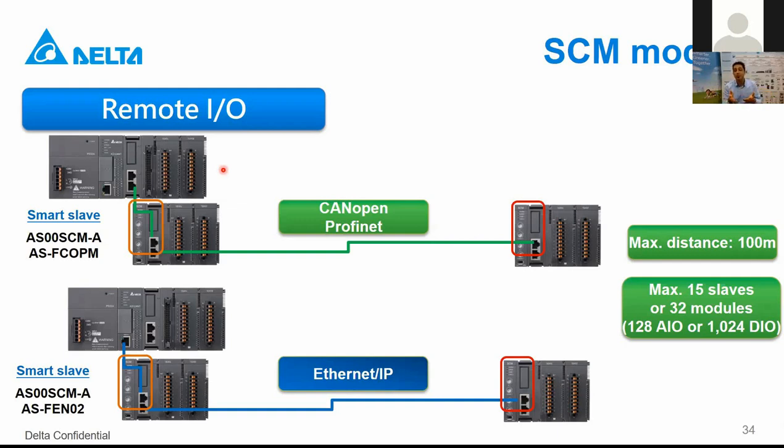So it is extra cost. Instead of that, you can make a small cabinet over there, and you use this communication module only. This is not a logic control. This is just a communication module, and you mount the function cards or I/O points nearby it. Then make the wiring to these modules. The communication card will send the status of the points of the modules to the CPU directly.